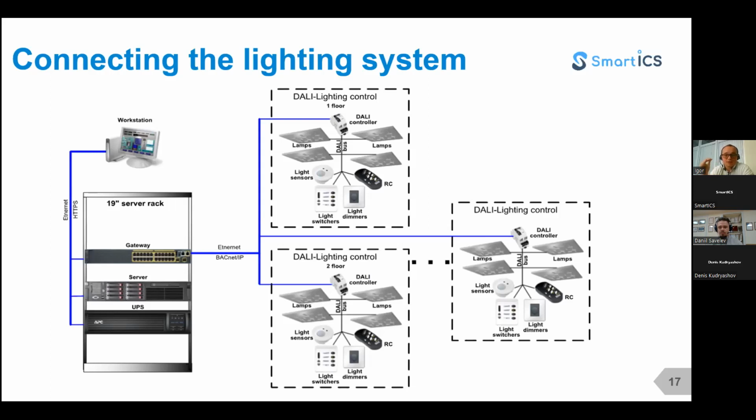They're very similar. The controllers that are gathering data from field devices, we're using BACnet for this specific reason. And again, the data are consolidated, gathered and transmitted to the server. From the server, again, we provide the data to the workstation. Any device could be your workstation, as you remember, and the software, SmartICS, is uploaded only to the server. This is also important to remember.